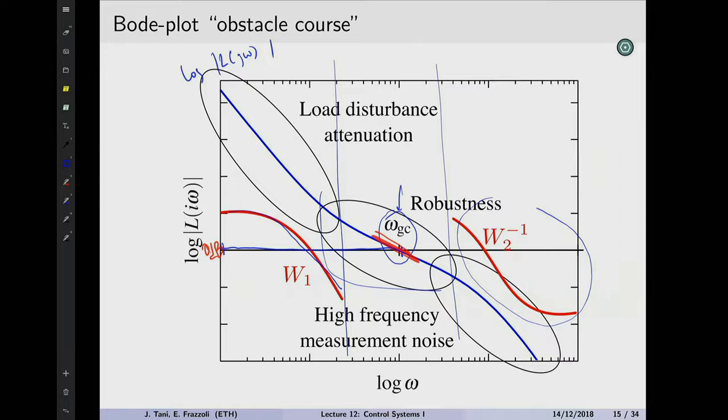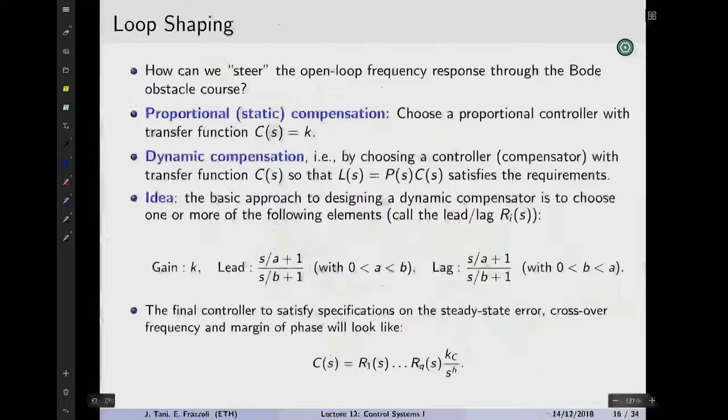So a good rule of thumb is having this slope be around 20 dB per decade when it crosses the 0 dB line. And the idea is as flat as possible. Of course, it can't be totally flat, otherwise there's no crossing of the line. Okay, we will continue later with how we actually get this to work.